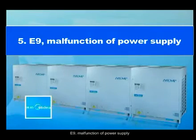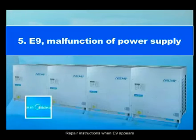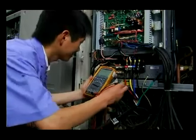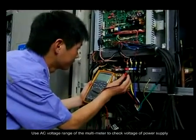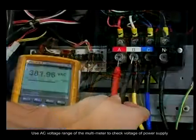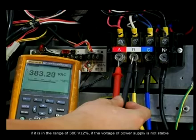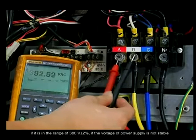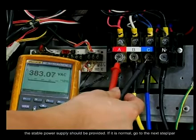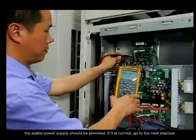E9. Malfunction of power supply. Repair instructions when E9 appears. Step 1. Use the AC voltage range of the multimeter to check if the voltage of the power supply is in the range of 380 volts plus or minus 2%. If the voltage of the power supply is not stable, stable power supply should be provided. If it is normal, go to the next step.